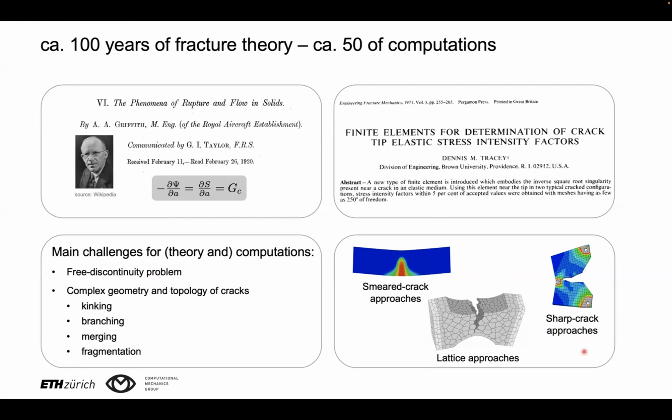And sharp crack approaches, on the other hand, can be exemplified by mentioning the extended finite element method, XFEM, or the generalized finite element method, or cohesive zone approaches using interface elements. Now, all these approaches have the disadvantage that they need to track the discontinuity, so to track the cracks.